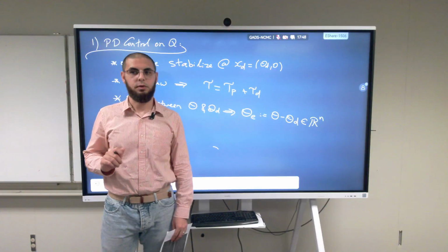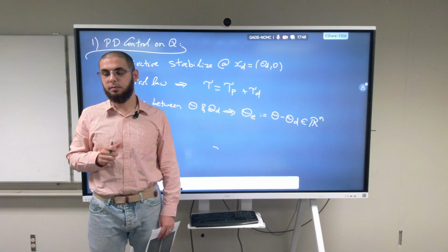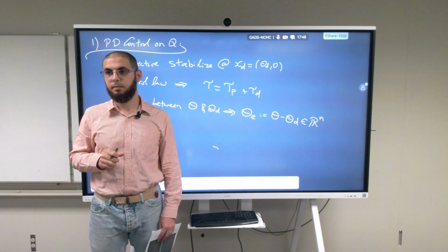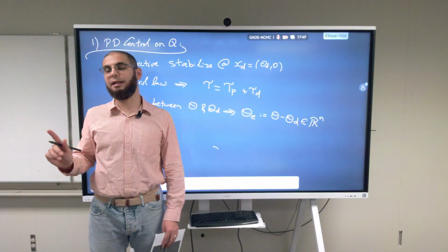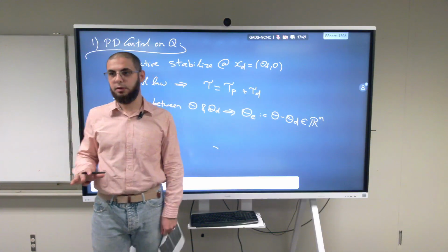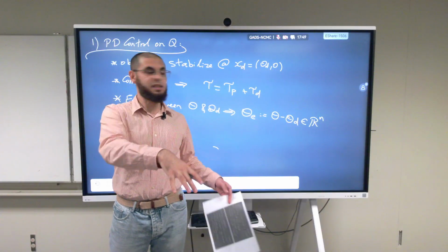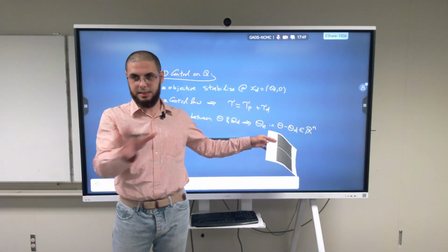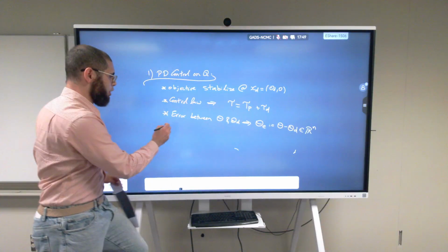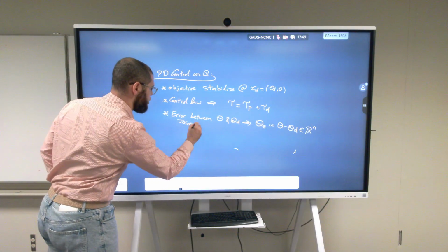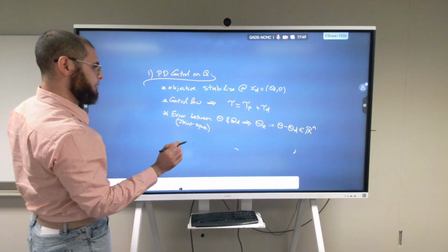No. So here we can say that at the configuration level, we can make it isomorphic to Rn. That's right. The workspace is not. And that's exactly what we're going to be looking at next time, when we look at impedance control. If you want to do stuff in the operational space or the task space, things will not be as easy as this. At the joint space, yes. So this is an error in the joint space, to be very precise. And something weird happened. I zoom out, right?